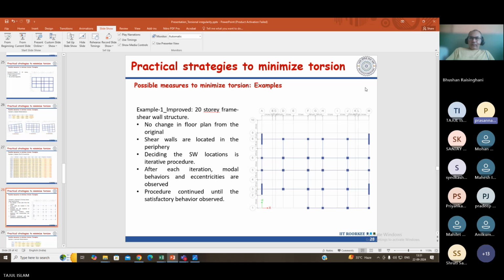Your equivalent bending moment and shear you are not checking for the wall design, like for the beam. Which reinforcement are you talking about? The shear reinforcement? Yes. While designing the beam, based on the analysis forces and torsion forces, you convert the torsion into equivalent bending moment and shear, correct? Yes. Accordingly, your stirrups and reinforcement will be given.